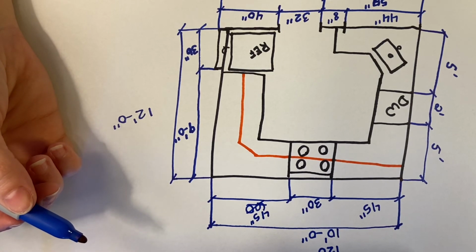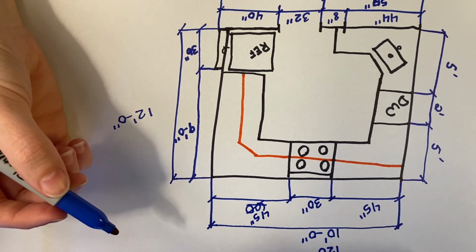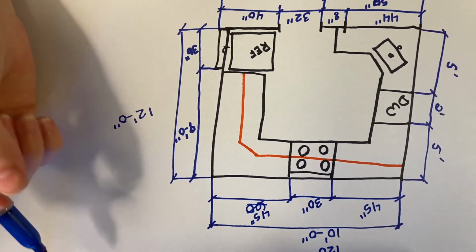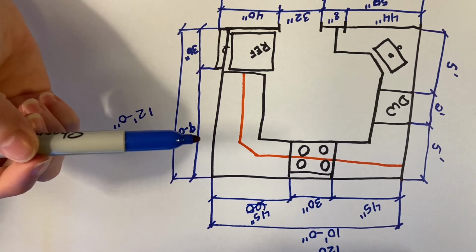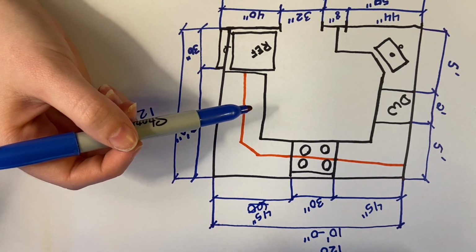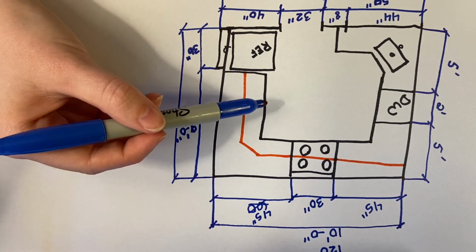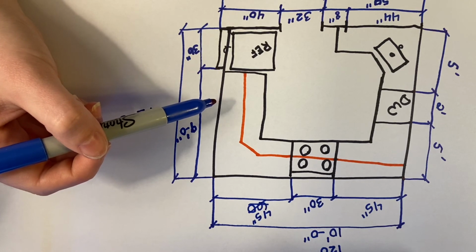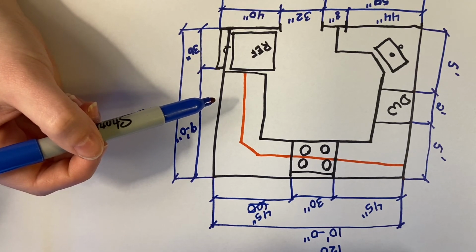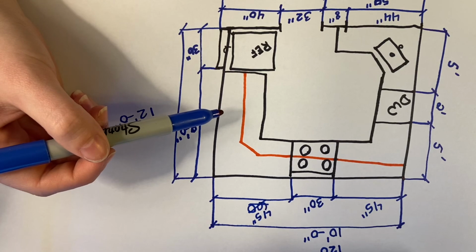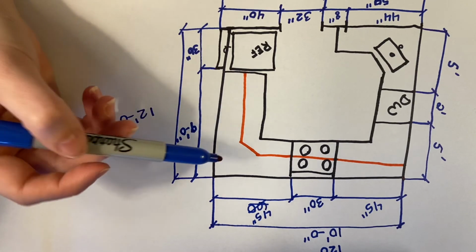The nice thing about cabinetry is unless you have something that was highly custom, you're looking at doing a simple double check of your measurement. All countertops are going to be somewhere between 24.5 and 25.5 inches from the edge of the countertop to the back of the wall. You know, your actual base cabinet is 24 inches, and then your countertop overhangs a little bit, but that varies depending on the kitchen. So if you do a double check and make sure that that's your countertop depth, you don't need to do any other measurements. Same thing with your upper cabinets.